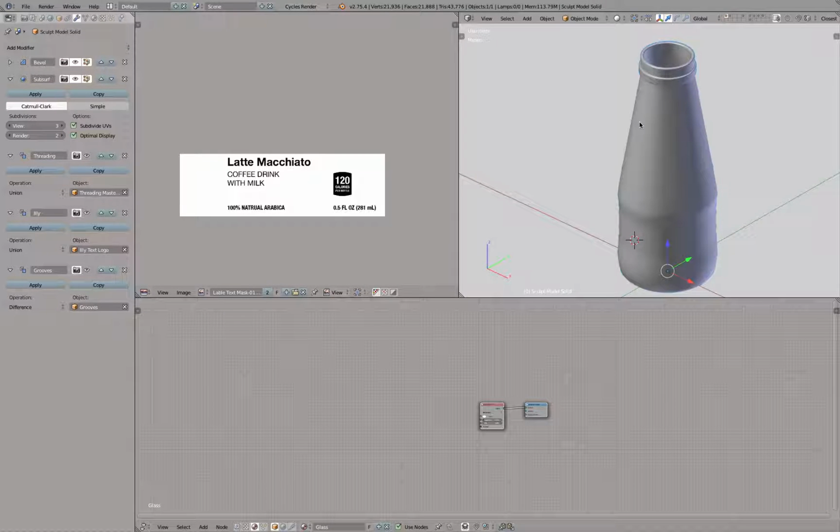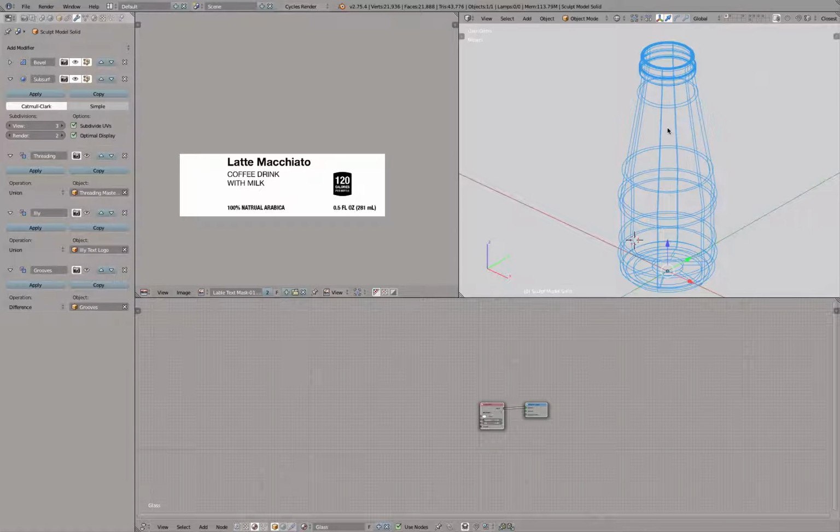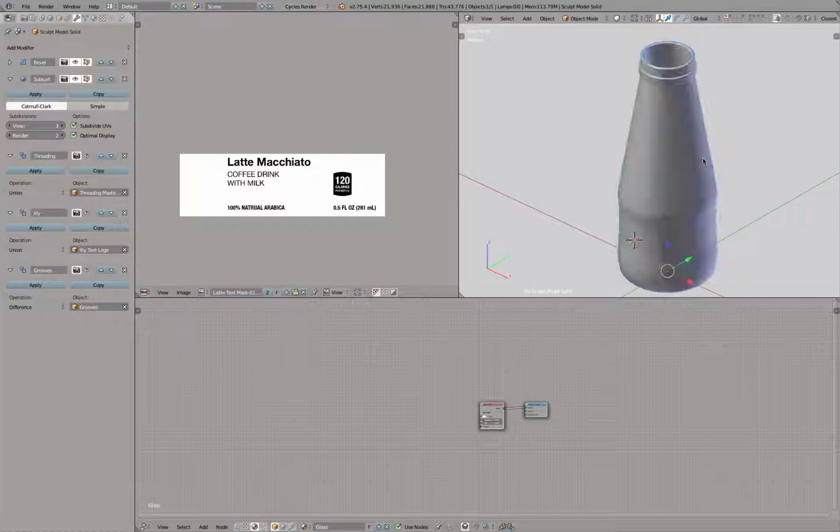Okay. Then actually right now I will do a Shift D copy, so not a clone. Normally you want to have a clone so that whenever maybe I change this one, the projection model for the logo will be updated as well. However, actually later we will put a fluid in here, so we have to change the bottle design a little bit.